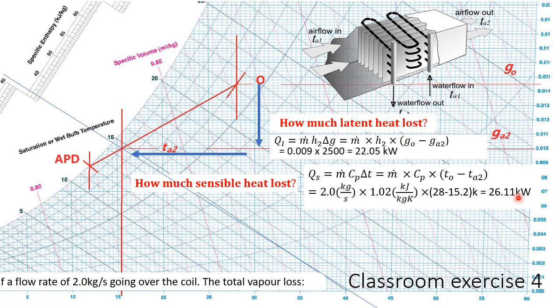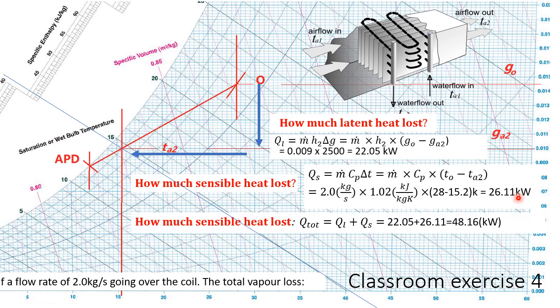Okay, so we use these two formulae to calculate latent heat and sensible heat. We put them together. So how much energy lost from outdoor air to off coil? Previously, before going in, it has so much energy and lost so much, right? So therefore, altogether, these two are added together. So 22 latent plus 26 sensible, we have 48.2 kilowatt. That is adding these two together.